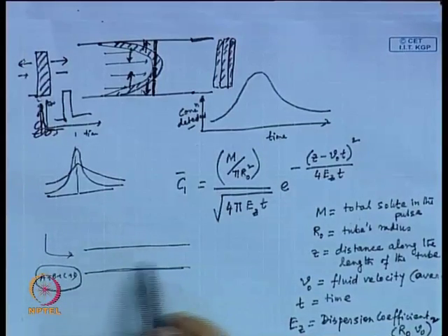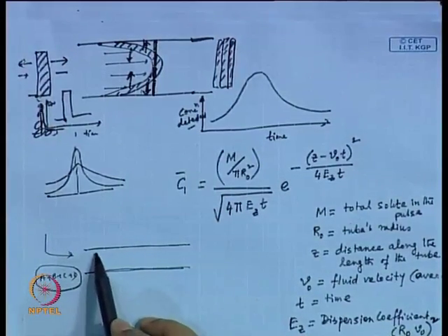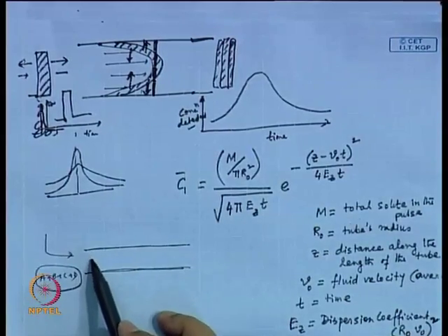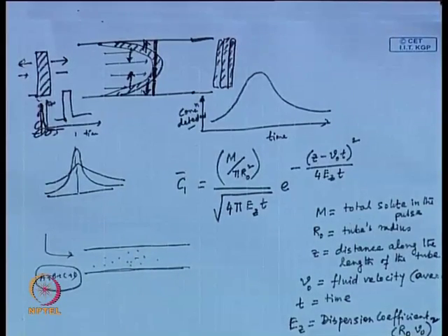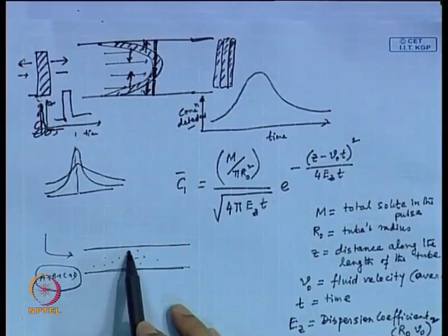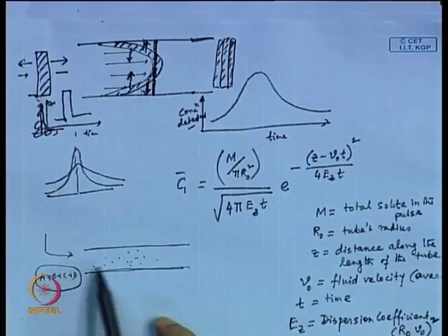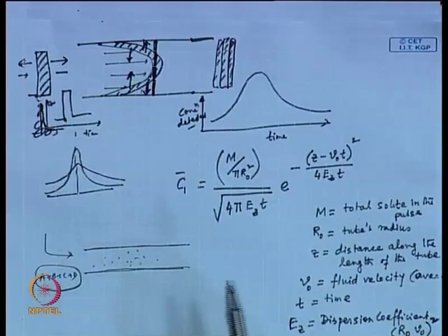Okay. And then you have this adsorbent. In a conventional chromatographic unit, you have a packed bed. Packed bed means it is a bed filled with beads, so flow can take place through the sides of these beads, that's the idea of a packed bed. Now, the wall is coated, it has a special coating, and this wall will adsorb. So, when A plus B plus C plus D are flowing, they have some preferential adsorption. Maybe A is adsorbed more, B is adsorbed less.